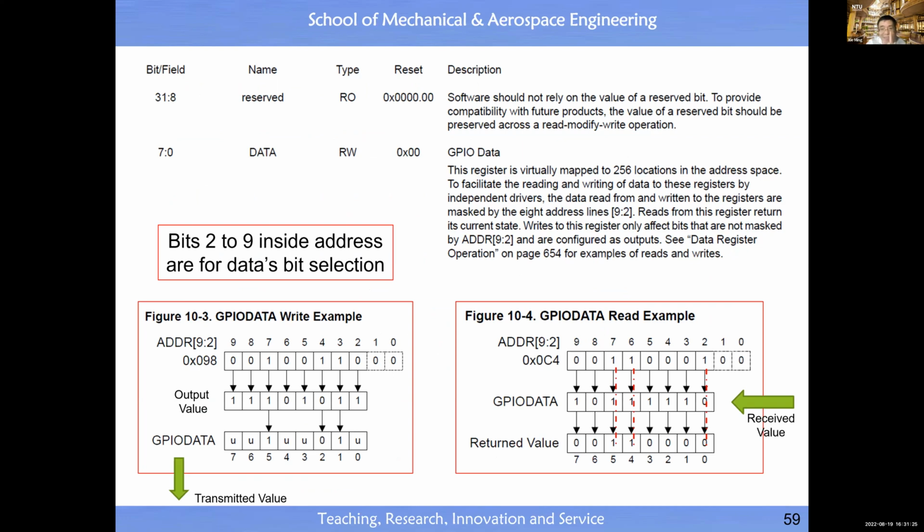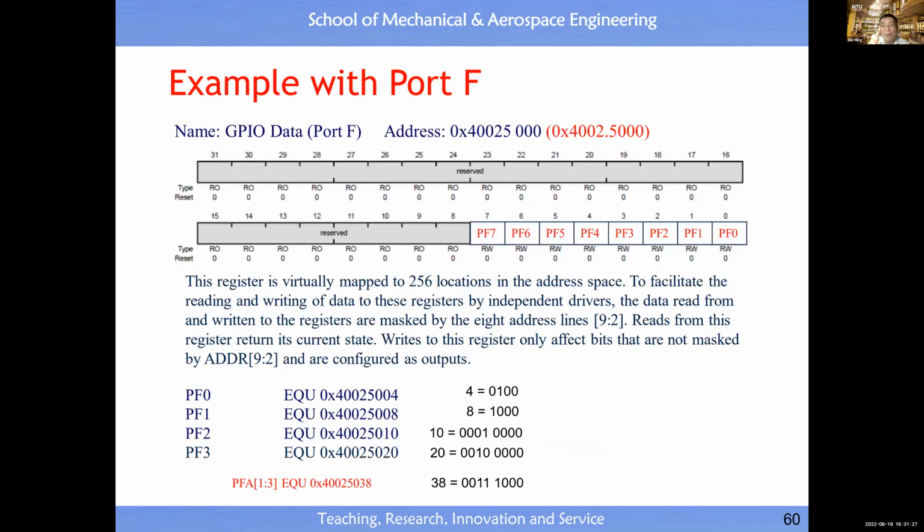Okay, so this is why it's very tricky. But tricky is difficult for your hacker to hack into your code, right? So bit 2 means it's 0, 1, 0, 0. Okay, bit 2 is 1. Then in hexadecimal number is what? Is 4. You write the 4 there. That means I only allow the data bit connected to pin 0 of port F to flow in, flow out.